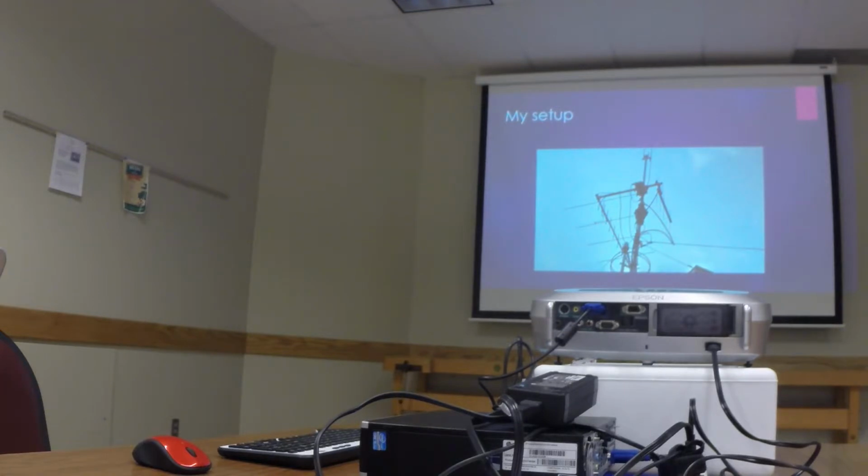Okay. Oh, Dan, I'm sorry, you had your hand up. This is a little bit different than maybe your project itself, but I'm perplexed. You were telling me that the amateur satellites are only basically operating 2 meters and 70 centimeters? Mm-hmm. There are a couple exceptions to that. There are some old Oscar satellites that downlink to 10 meters, and there are some newer satellites that go uplink or downlink on 2.4 gigahertz. Okay. 10 meters to 15 meters even. Sometimes 15. Yeah, Oscar 7 is still operational. It goes up on 2 meters and down on 10 meters. 10 is not a worldwide band, so there's no incentive for you to put a worldwide satellite on that band. Okay, thanks.